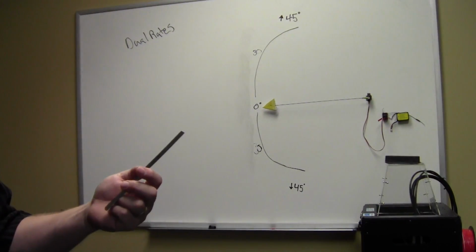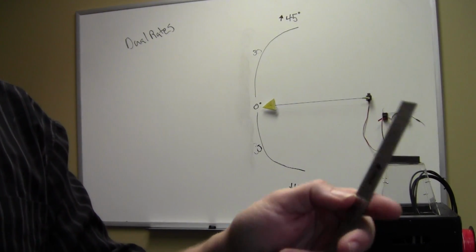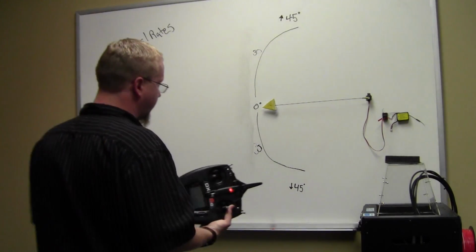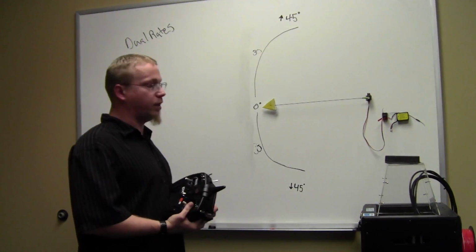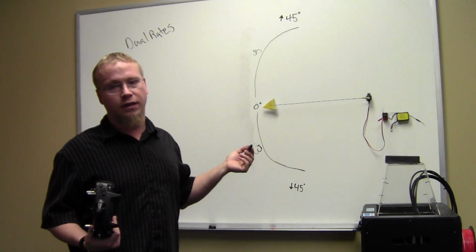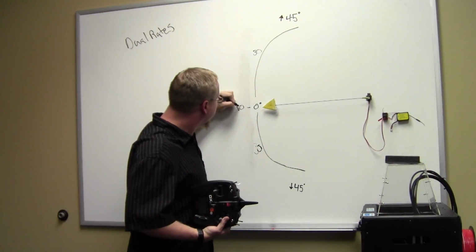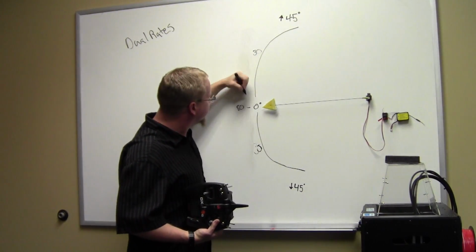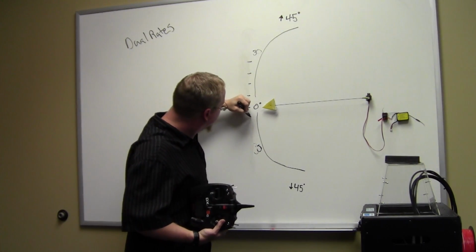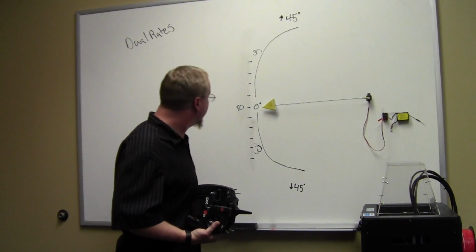What I like to do is try to find a middle point on my ruler, like let's say 80 millimeters, and go up and down from there. So let's pretend this is a control surface, and our manual says it wants 20 millimeters up deflection. We'll start in the middle at 80, and we'll make little increments of 5: 5, 10, 15, 20.